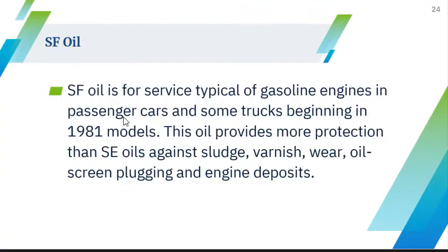SF oil is for service typical for gasoline engines in passenger cars and some trucks beginning in 1981 models. This oil provides more protection than SE oils against sludge, varnish, wear, oil screen plugging, and engine deposits. Notice that this is an open-end series. So when the car manufacturers and oil producers see the need for other types of oil, they can bring out the SG, SH, service rated oils, and so on.